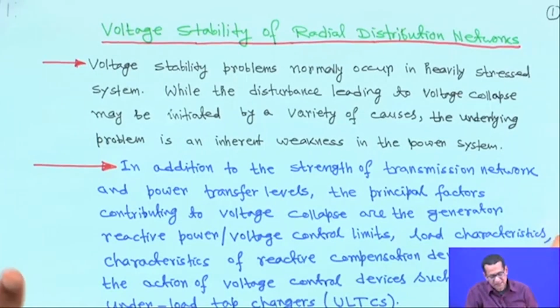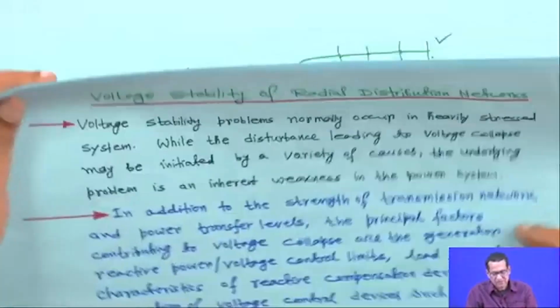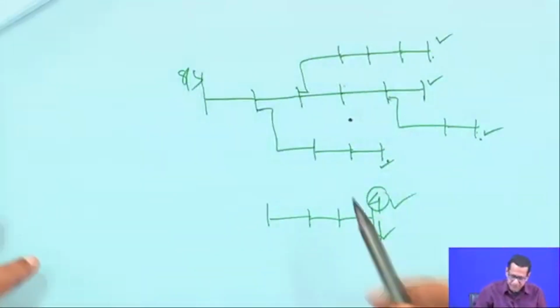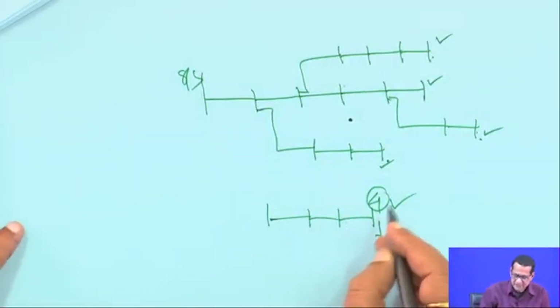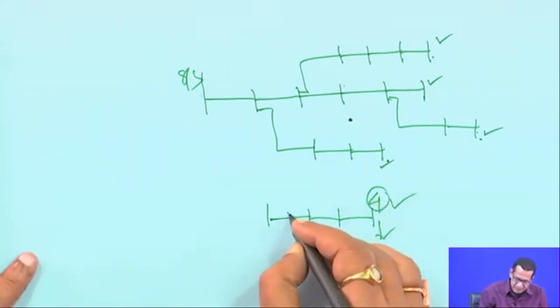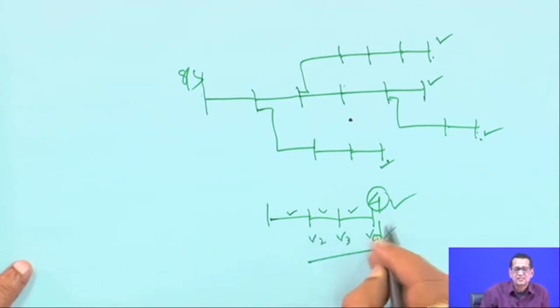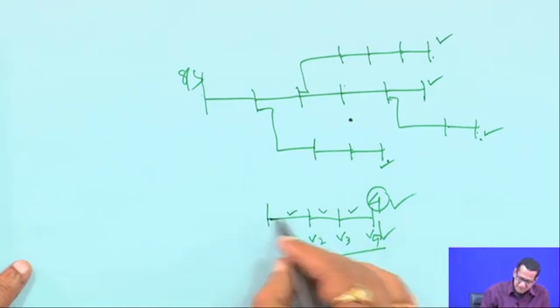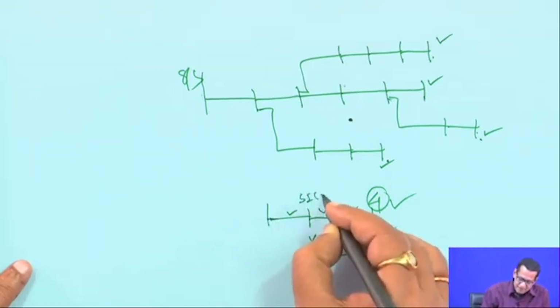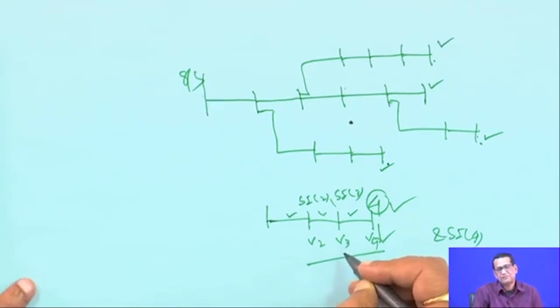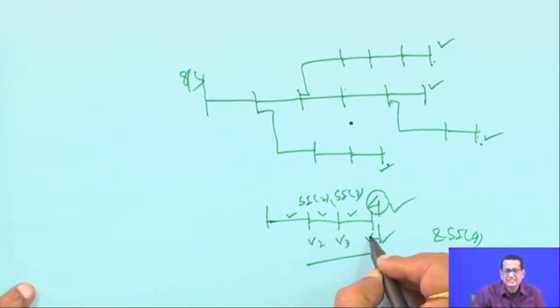Suppose a load flow will be given, I will suggest one thing to you for this 4 bus example. What you can do is neglect the losses. If you neglect the losses, we have computed V2, V3 and V4 in the second method by neglecting the losses. Suppose loss is neglected, you yourself compute what is the value of SI2, SI3 and SI4. Just neglect the losses. These results are available in the very first iteration when branch losses are neglected.